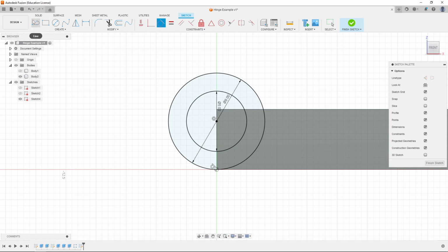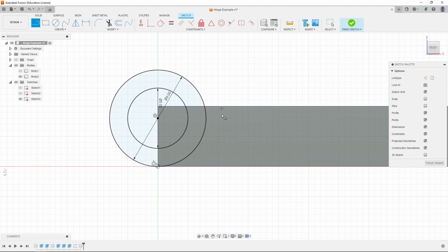We'll create a line with the line tool. It's going to be a vertical line, so it doesn't really matter where it is right now. When I select it, I make sure it's straight down. You can see that right angle little blue square at the bottom, so it is a straight line. Notice the line is blue because it's still technically free to swing side to side. And then we'll once again use the tangent constraint to snap this line to this circle. And of course the line moves because if the circle is locked in place and all black, it means it cannot move. Then the line was the only thing that was able to move. And now they're all black, so everything's in place. So our sketch is complete.